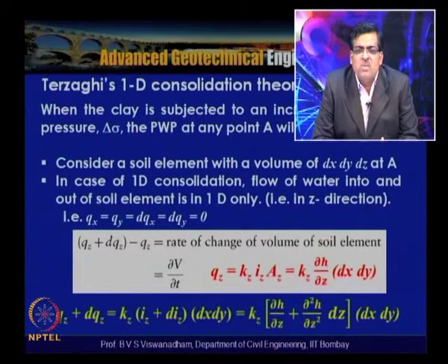Let us assume, for this example, a soft clay loaded with an area fill of about 1 or 2 meters extending over the entire area. Then the extent of the area is much larger than the thickness of the clay layer, and one-dimensional consolidation predominantly happens.